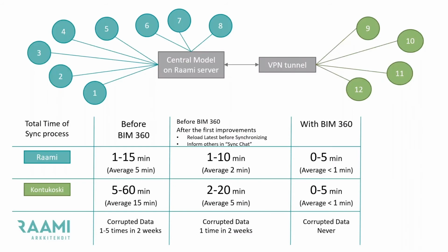Actually, to be honest, we had that once, but it was our own mistake because we had some files still linked from our own server. We didn't load all the links to BIM 360 first when we started the testing process. But then we saw that this is something you really need to do, that you can't load anything from the server if you are working remotely from home. After that there was no corrupted data.